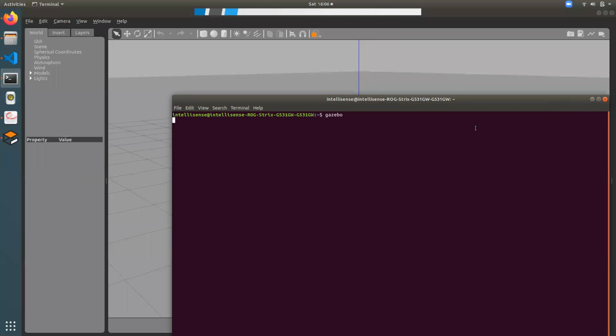For the ease of simulation, they have created a bridge between ROS and Gazebo. If you go to the packages, you will see a package named gazebo_ros, which is the bridge between those two. Now they ship the Gazebo simulator along with ROS as well, and with that bridge between them, we can use Gazebo to simulate the operations we do in ROS.